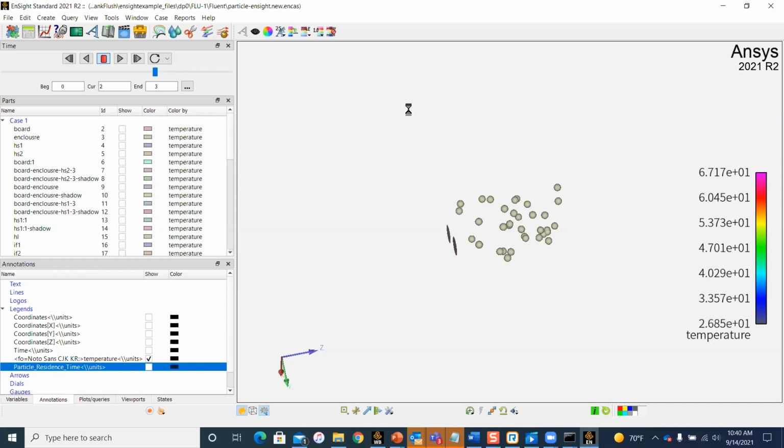And I think another question was, what is the execute command setting for? A good thing about EnSight is that you can record all the steps that you are following in order to post-process your results, and then reload those same steps for another case, right? And you can do that in two ways. Somebody said, how do I save a file in EnSight? Well, you save a context in EnSight, right? So you have the same context, or the same set of commands that you've applied to one file, applied to another file that you load at a later stage.